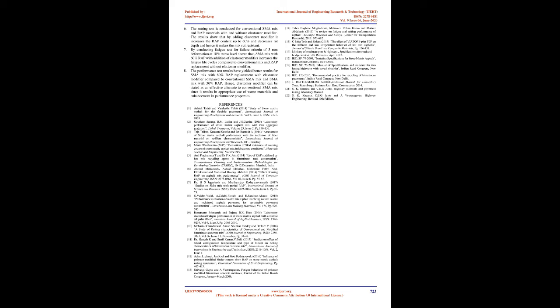3.5 Repeated Load Fatigue Test. The fatigue test is conducted on the conventional SMA mix and optimized wrap with and without the Elastomer Modifier. In this test Marshall specimens of 32, 28, and 25 blows respectively are tested in 4-point loading apparatus. The stress level and deformation are kept constant, which is 10% and 5 mm respectively. The test was carried out to find out the resistance to deformation due to repeated wheel load. The test results are shown in Figure 3. Figure 3. Fatigue results of different SMA mixes.